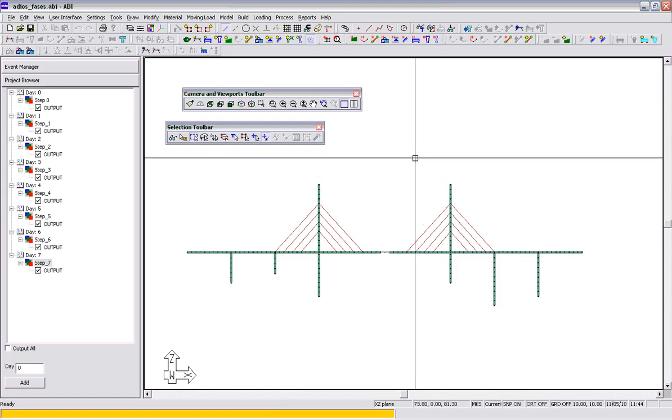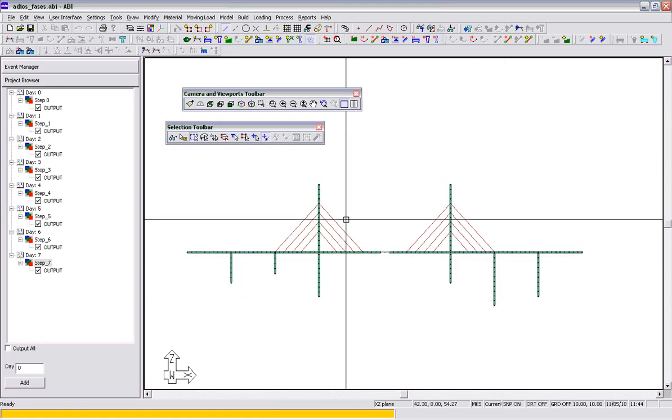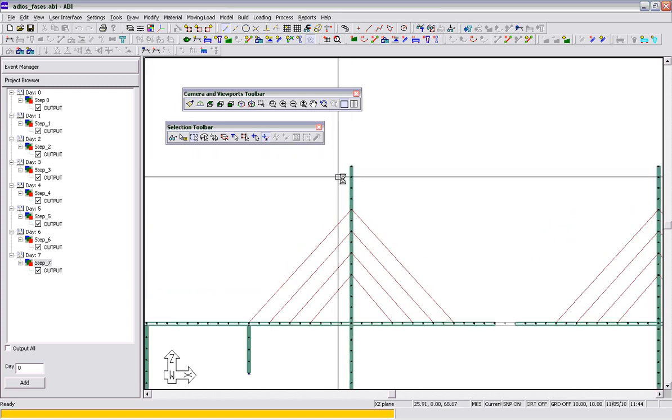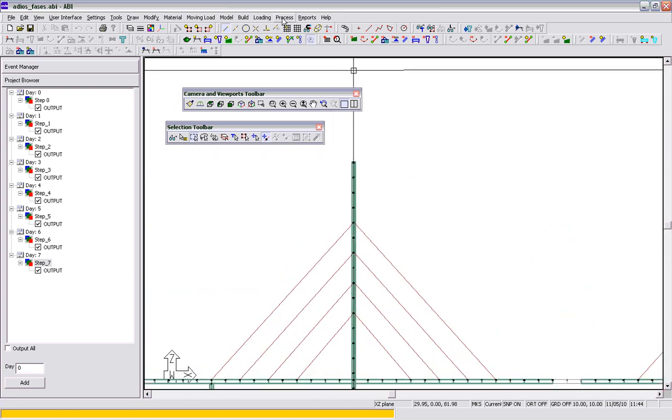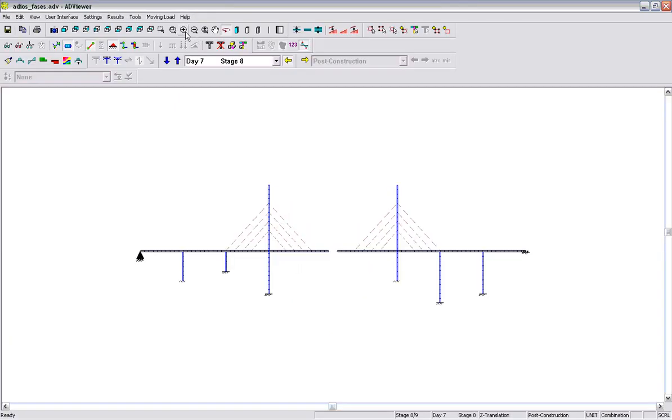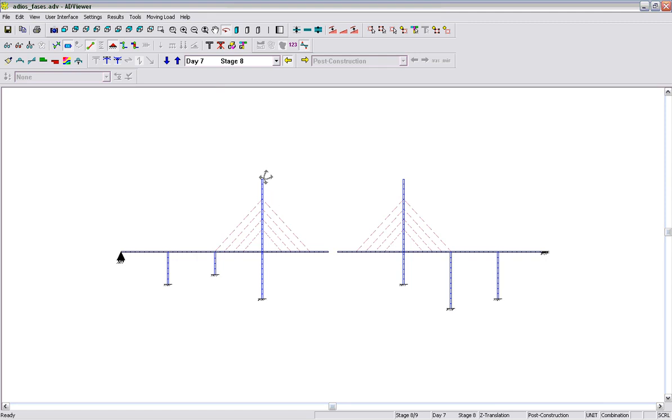Now, in some cases, when you first generate an input file, the node numbers on the main interface will not match those in the graphical viewer. So in order to interpret results due to that problem, what we can do is just turn on the nodal values shown in this viewer and match those with the output in tabular form.